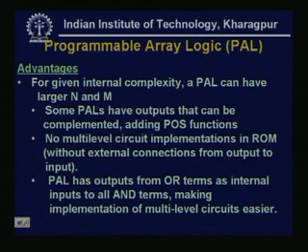Now, what are the advantages? For a given internal complexity, a PAL can have larger N and M, because it has a programmable AND and fixed OR. So, it can handle larger input variables, as well as a fixed OR.